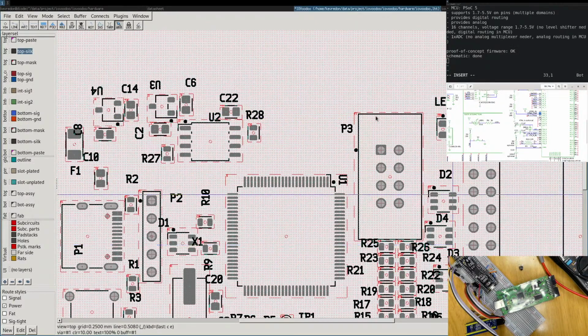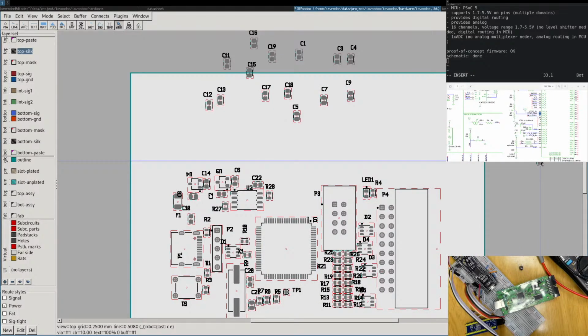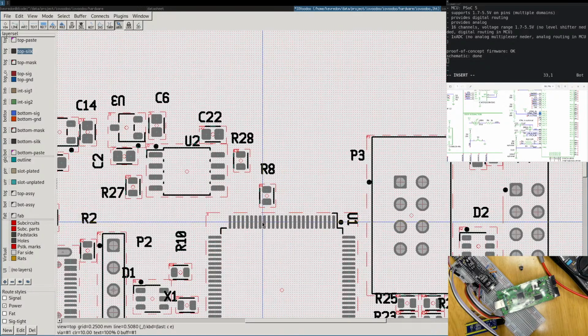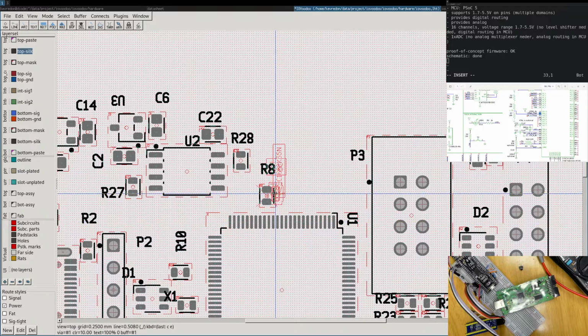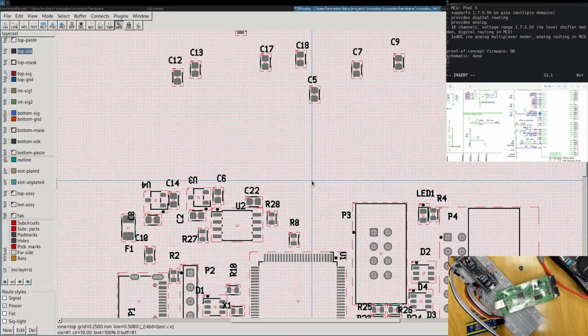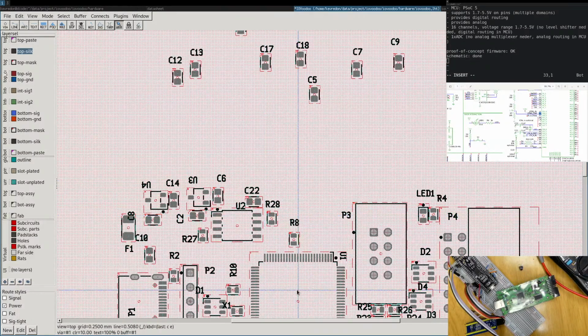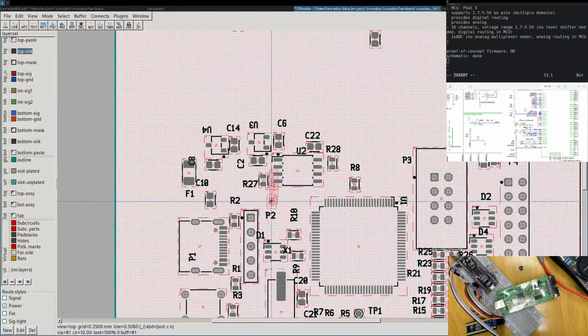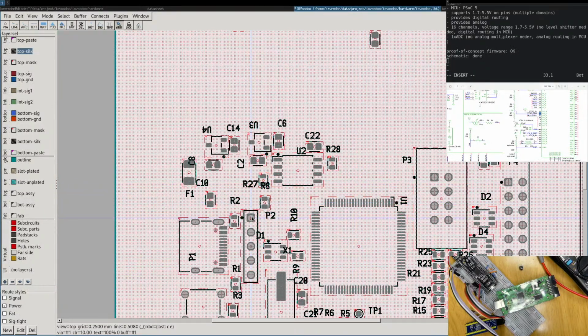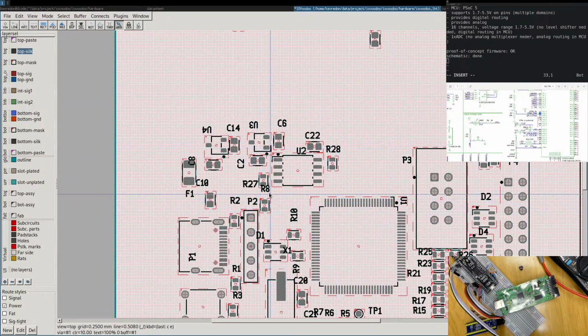For the reset, we have R8 and C9. R8, that's the last resistor we have. It goes in here, and then this doesn't need to be next to the microcontroller. Let's not put it next to the microcontroller. Let's put it here next to this. This is reset, ground, 5-volt ground, reset. Let's put it next to it, so it cleans the input of this R8 and C.